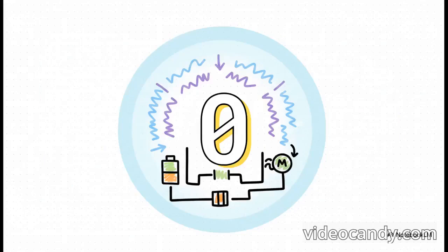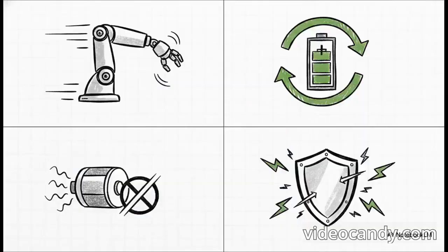But on the right, that's the position response with a stable DC bus. Just look at how cleanly the actual position, that dashed line, is tracking the command. That right there, that's a picture of a machine in total control. Ultimately, the goal is this number, 0, or as close to zero position error as you can possibly get. And having a stable DC bus, where all that regenerative energy is managed correctly, is what makes this number possible.